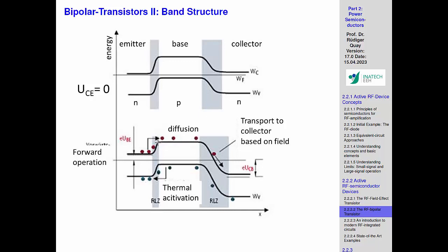And the trick is then that at some point they diffuse further and are caught by the relatively strong field, you sliding down the water slide. So it's this little kick, and if it catches you, you're going down a very long slide. And that is the reason why we have an additional effect which favors the amplification so much. It's this combination of sharp profiles, induced by diffusion, plus proximity to a second PN junction.